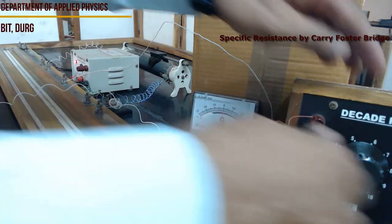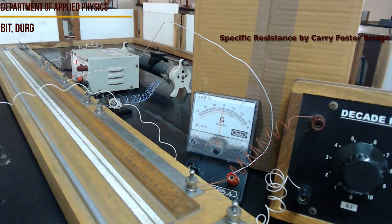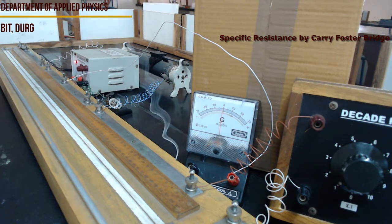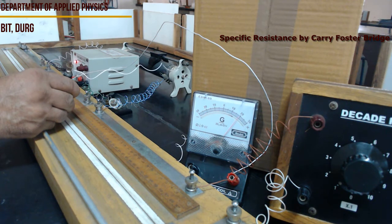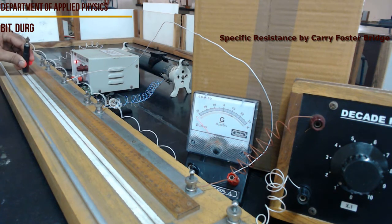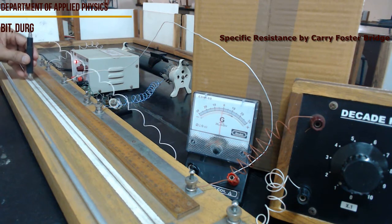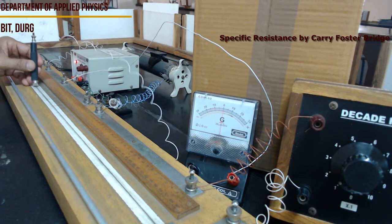I am going to produce a resistance of say 0.1 ohm on the resistance box. Again I am going to find the null point. As you can see, on this side the deflection is to the left, and on this side the deflection is towards the right. So in between these two I must get a position of the null point.